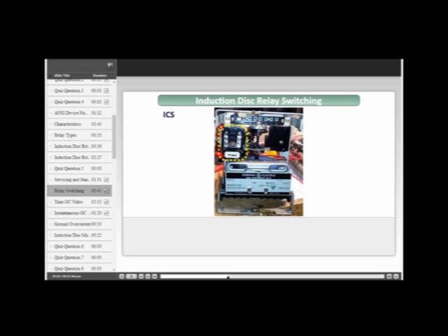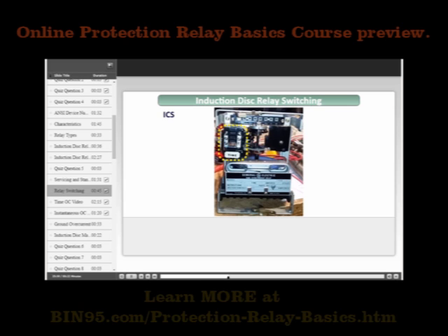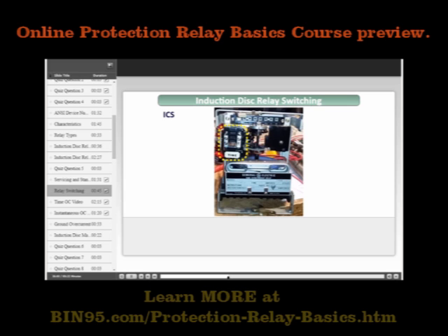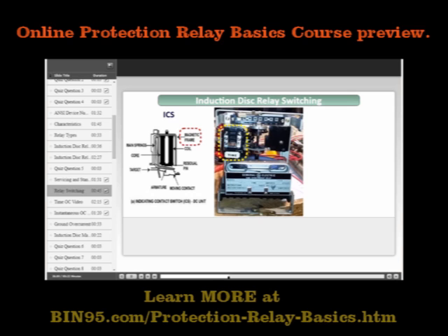Here's a closer look at the indicating contact switch. The ICS unit is commonly used to provide a seal-in around the main protective relay contacts. It consists of the magnetic frame, the coil, residual pin, moving contact, armature, core, mainsprings, and target indicator.